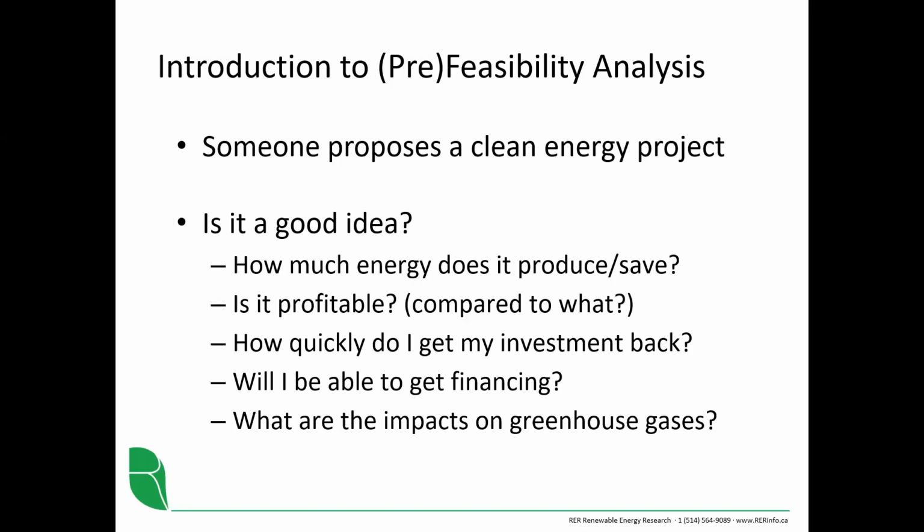So a feasibility analysis, say for a wind farm, is quite involved, right? You may have to install a number of different wind measurement towers and other tools like LiDAR on site, leave it there for a period of, say, at least a year, analyze that data very carefully, and do a lot of other studies related to everything from foundations to environment and grid interconnection.